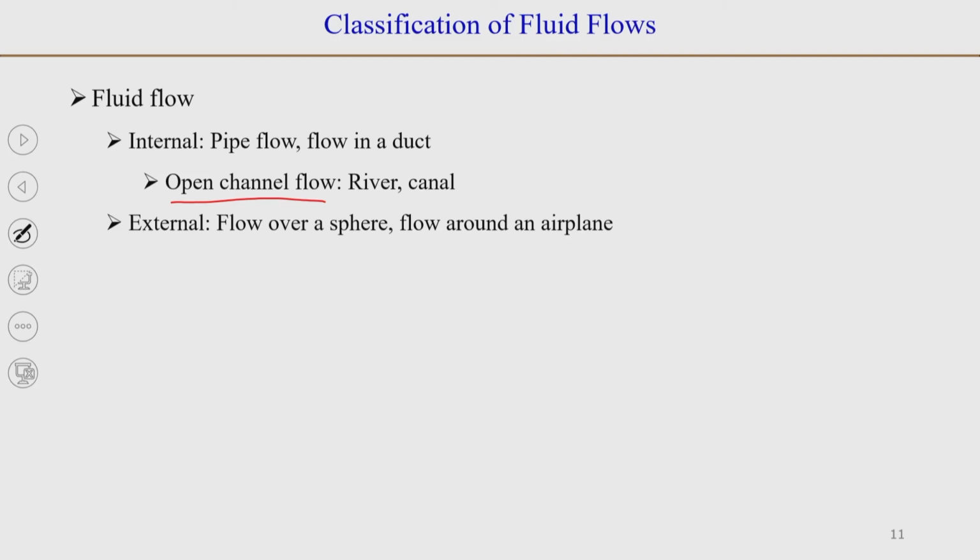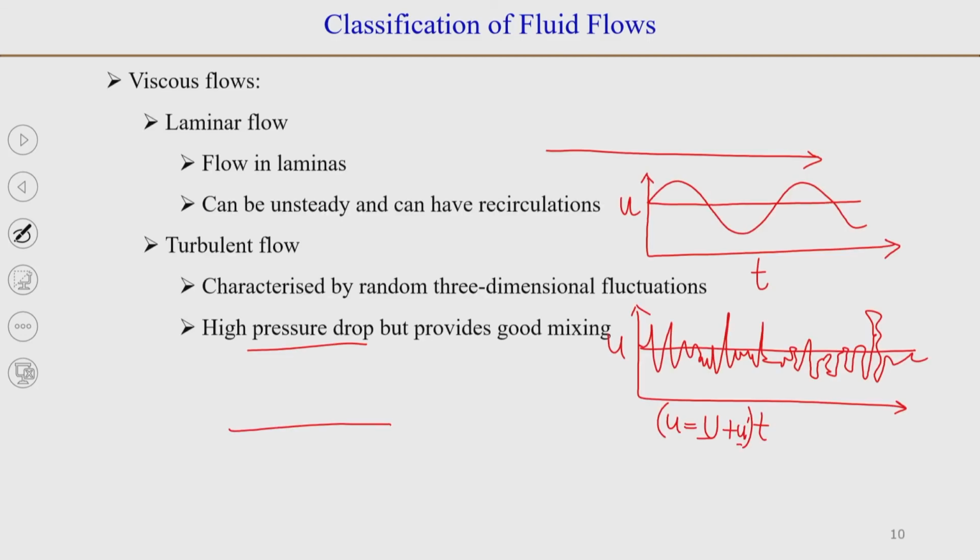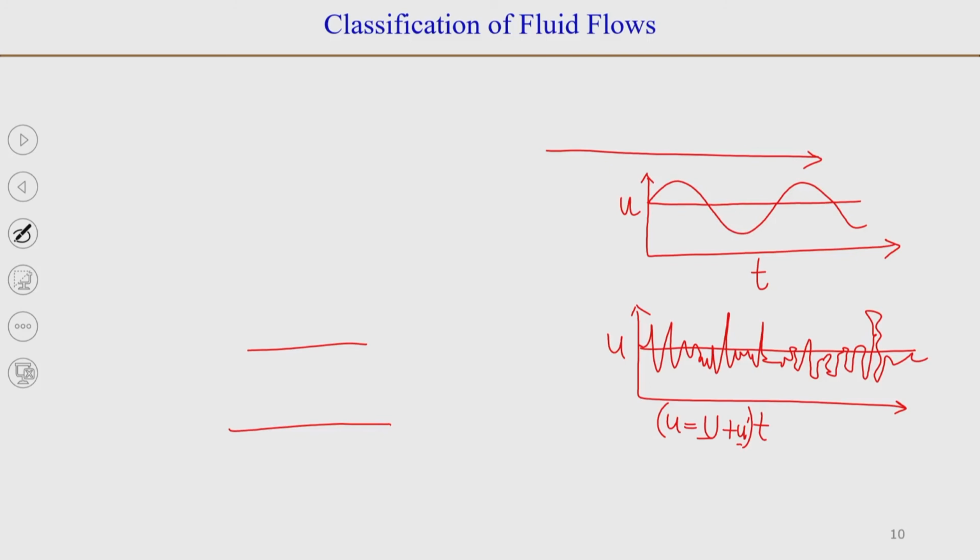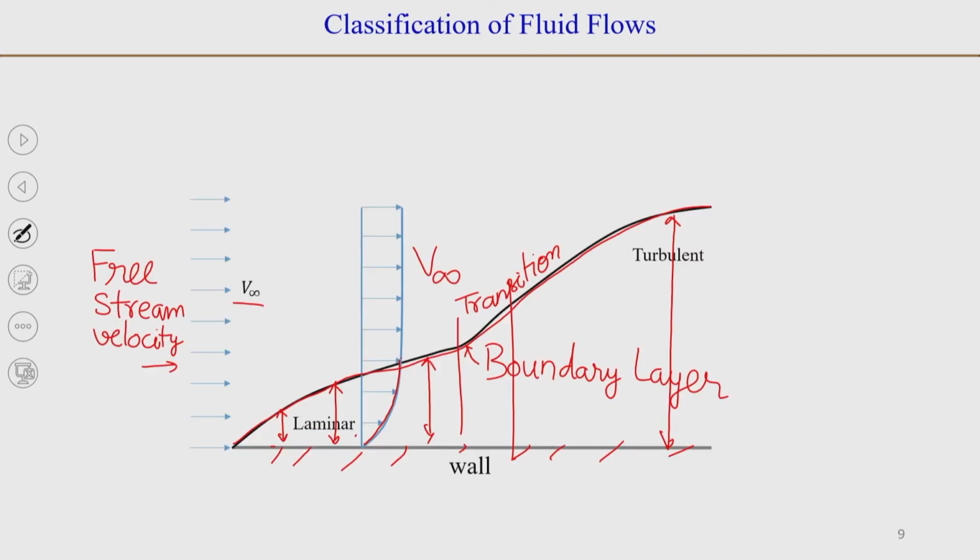Now, one important point we might want to go back and look at is when we defined the Reynolds number. For a pipe flow, the definition of the Reynolds number is rho u L over mu, and what we need to know is, what is this L and what is this u.